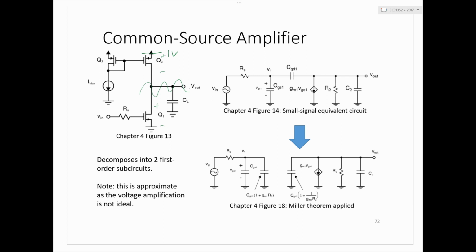So the common source amplifier is also, the analysis of it provides the basics of the differential pair because it's an equivalent half circuit for differential pair, which is a really important circuit. So lots of reasons why we're going to review this.